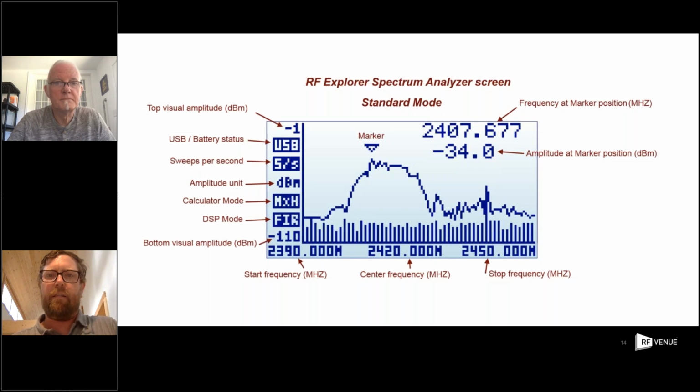They're sensitive and they're made a certain way, where overloading the front end or putting too much signal into them is really problematic. So in terms of looking at transmit signals, you can definitely do it, but the real core capability for this unit, and I think a lot of spectrum analyzers, is understanding what signal is going into your wireless microphone rack.